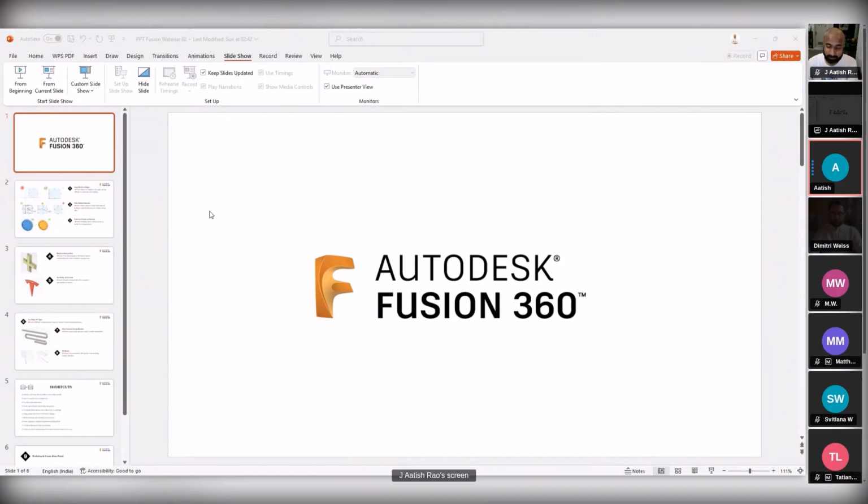Let's begin with this webinar. So this is all about how students are making certain mistakes in Fusion 360 and certain features they are not understanding. So first we will quickly know about the first mistake, that is the sketches that are not aligned to the origin and which causes difficulties in constraints and modeling.